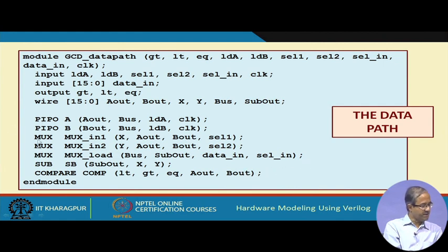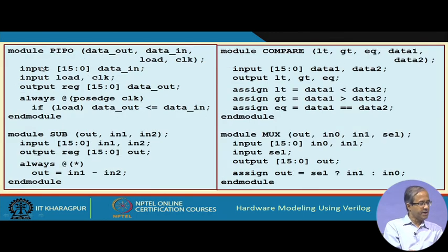Right now, a very quick look at these descriptions. Here, for the sake of convenience, I have shown all of them in a behavioral fashion, but in a real design, when your target is to achieve higher performance, we often design many of the modules in a structural way, so that we have entire control over the way this circuit is designed. Because when you design in behavioral fashion, we leave it entirely to the synthesis tool to decide what kind of circuit it will be generating.